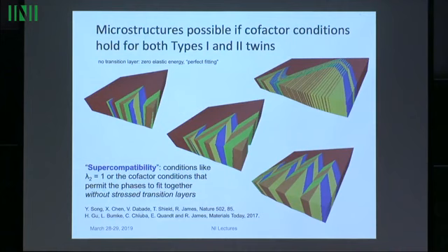And in these materials, no matter how clean you make the material, there are always non-transforming defects in the material. And to accommodate these, it can be quite useful to have these different ways of fitting together the phases. For example, around a non-transforming defect which is relaxed in the austenite phase, you can use these microstructures to make a bubble of austenite, which doesn't transform, but it's only a small region and is completely compatible with the martensite around it. That can be very useful.